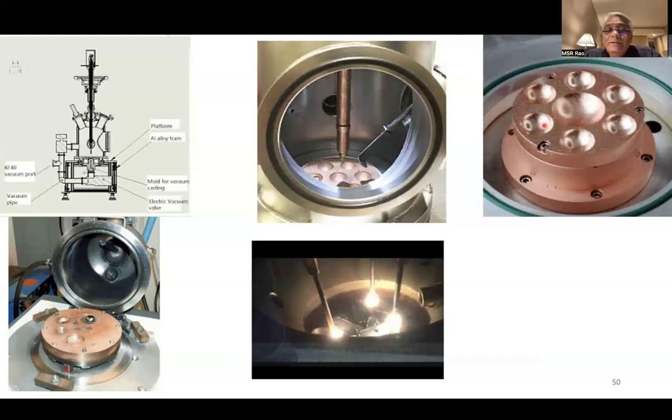You might think that by taking 60-40 of element A and element B by weight percent, you melt them, and you end up getting a 60-40 ratio of the melt. No, it need not happen. Because if the vapor pressures are largely different, the final composition, the atom percentage or weight percentage, will be completely different from what you started with. That's where you need to compensate.